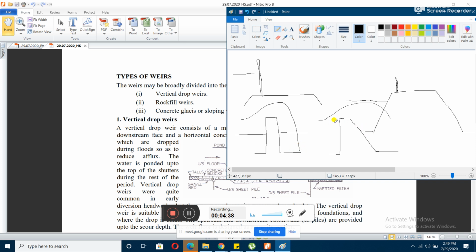So in order to avoid that, they have just made this one inclined, so that the water jumps and falls on this, and this is going to be absorbing a lot of impact. The water is going to come around, like this, and fall on this wall, and absorb the shock, and this part of the floor is not going to be affected. So this was being adopted, and on further correction, it was seen that the water is coming like this, hitting this surface perpendicularly, and the effect.